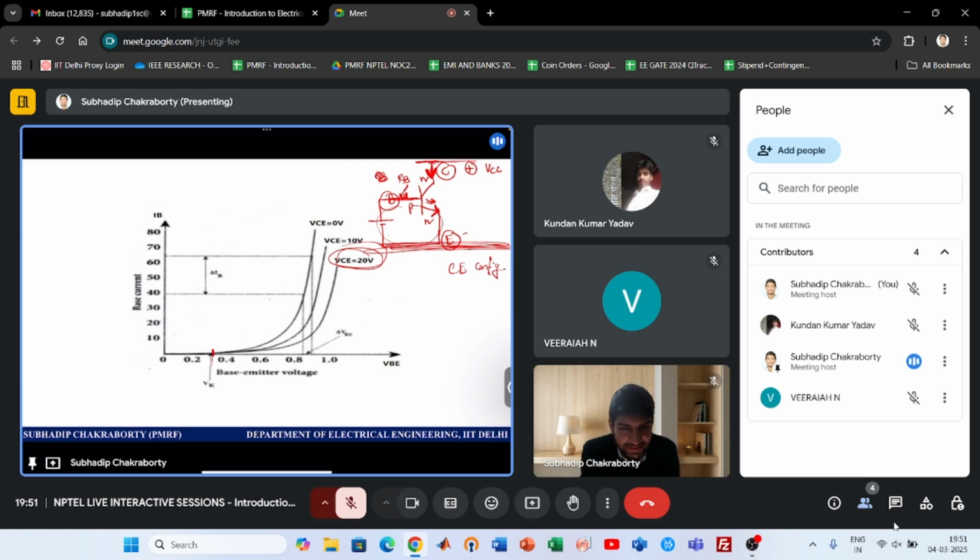For a different voltage applied across the base, you can control the base current, because controlling the base current means controlling the flow rate of the charges. Now obviously that can be done with the help of a controlled resistor, that is a different resistor. For a particular application you can use a fixed resistor and a very wisely chosen voltage VBE, because the base voltage impressed through the base terminal of the transistor is very important. If it is very high, then it may damage the device. So that's why we need a resistor, which we call the base resistor.